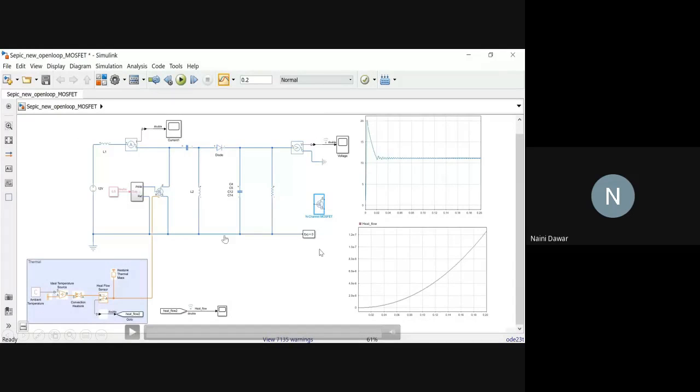So what is being done in this case is, we use the N-channel MOSFET switch. Unlike the linear switch, this is a non-linear semiconductor switch, and you can put in all the dynamic, ohmic resistance and the static parameters from the datasheet, simulate the component, and compare the results with the datasheet results. You can validate the results also. Then put it in your actual circuit.